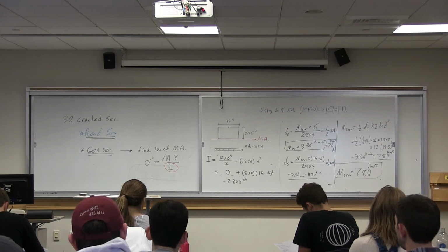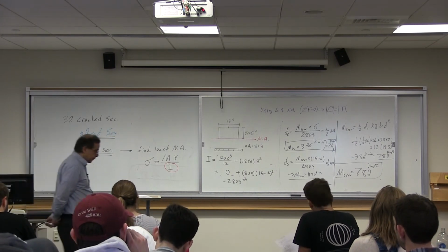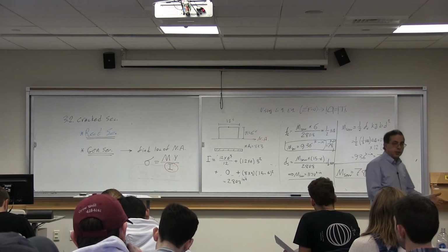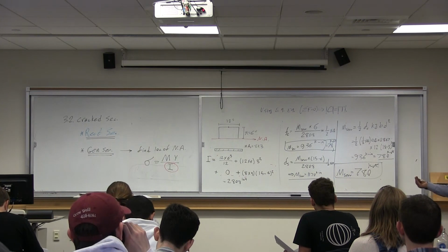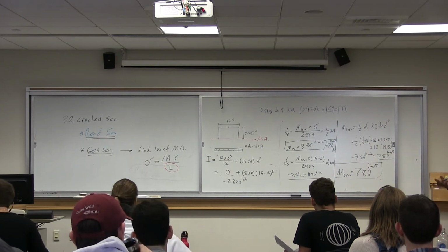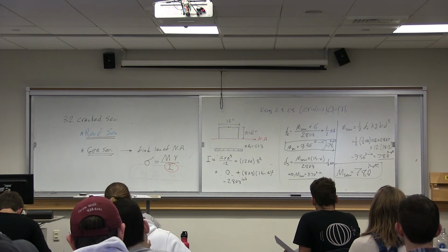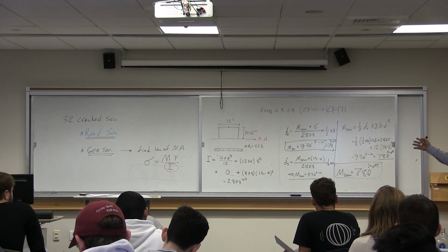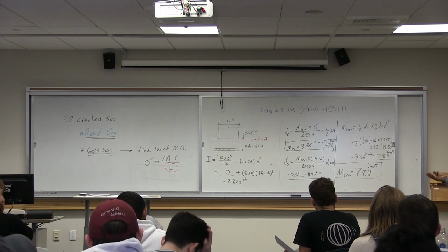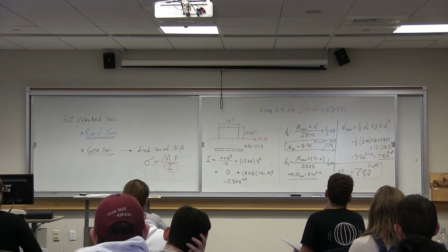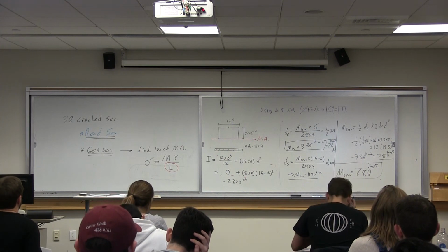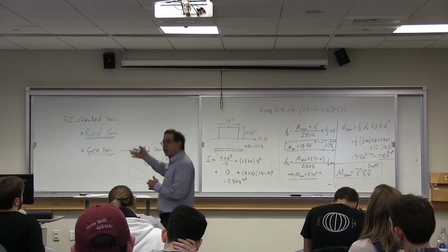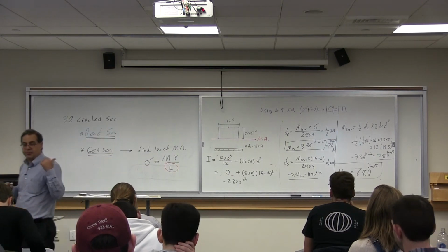First one. Why? Because we already have the formulas for the rectangles. And you don't need to calculate the moment of inertia. The first one, you just plug in values and you solve it. If your section is rectangular, usually the first method is easier. Can you solve it this way? Sure. The only thing added is I. If you calculate moment of inertia, then you have an equation here too.